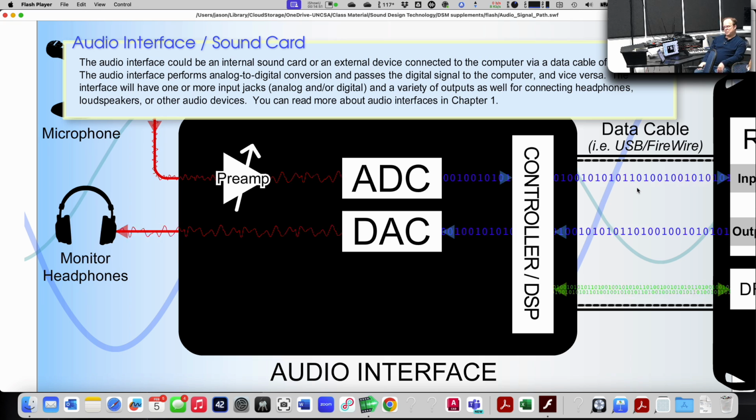because everything makes noise, and one of the dangers of putting that interface inside of a tight laptop or something is it ends up being packed in around a lot of noisy things and other circuits that could inject things you don't want into that signal before it gets encoded into digital. But generally speaking, the audio interfaces that are built in tend to work much better as digital to analog converters, meaning output. They're much better as output devices than they are as input devices. The input side of these built-in audio interfaces is usually not very good.